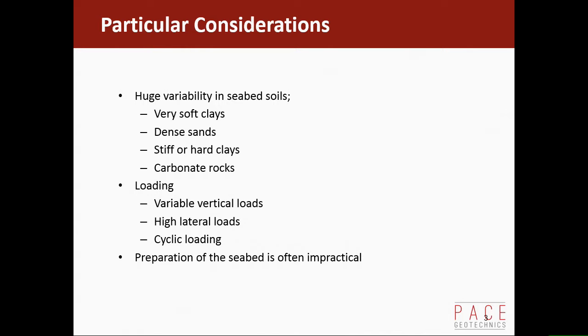And the other main difference with subsea structures is we land it on the seabed, but we very rarely get the opportunity to prepare a nice flat area for it. You've got to either survey it and satisfy yourself it is sufficiently flat, or you might put rock dump down to level it off, or you design a system which penetrates into the seabed in some way and reduces the need for preparation.